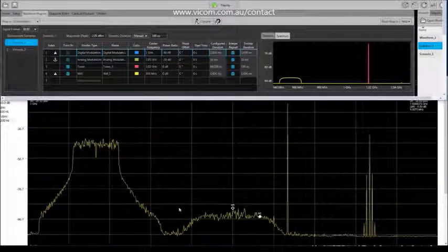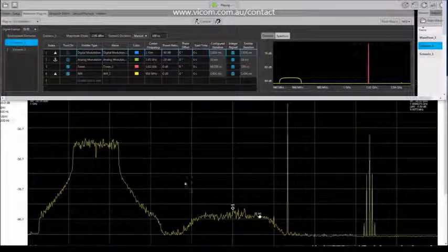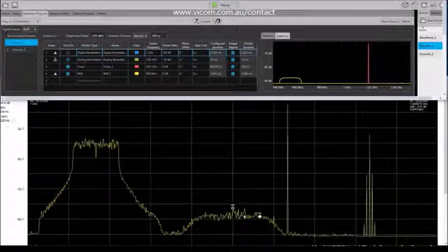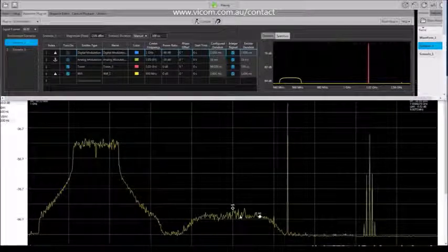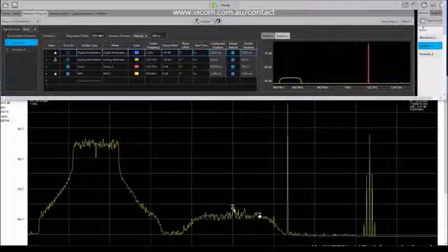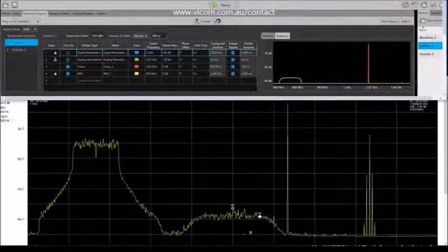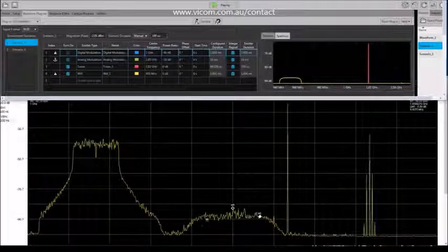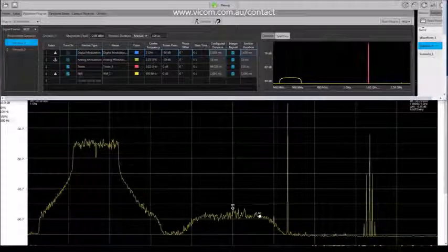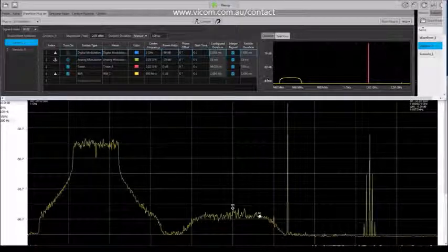So now I've configured it using 2 channels of the AWG, where we're power splitting the 2 channels, and you can see that now we've pulled up this minus 60 dB signal so that we can actually see it using the full dynamic range of the AWG. So this is just another method of being able to view signals that are pretty much buried in the noise of a single DAC system. This is a great capability that's also available when you're using the environment plugin for these particular types of testing.